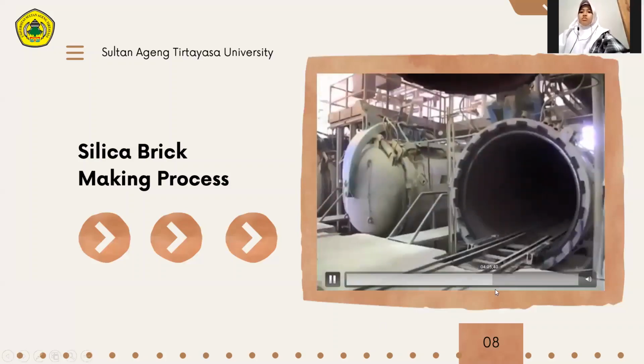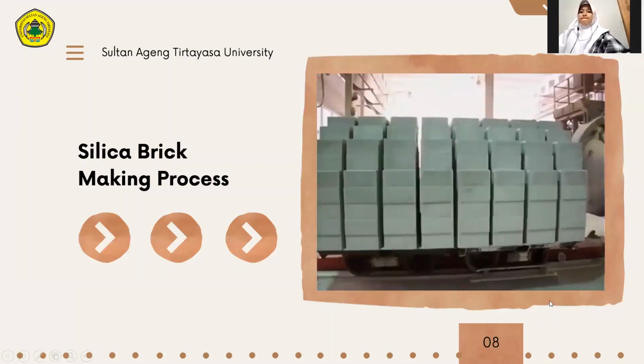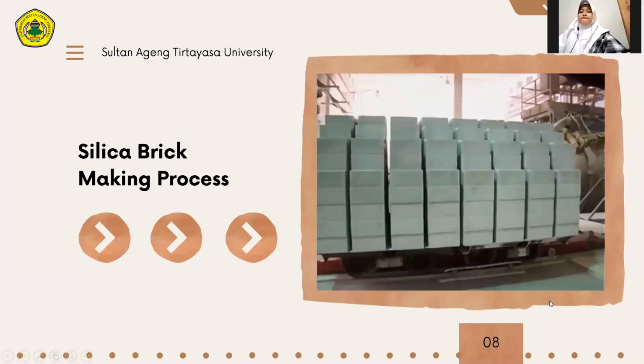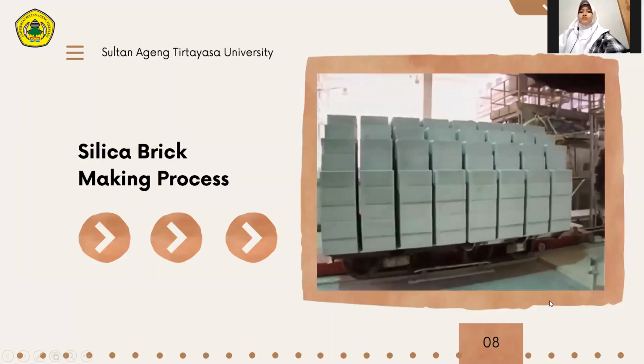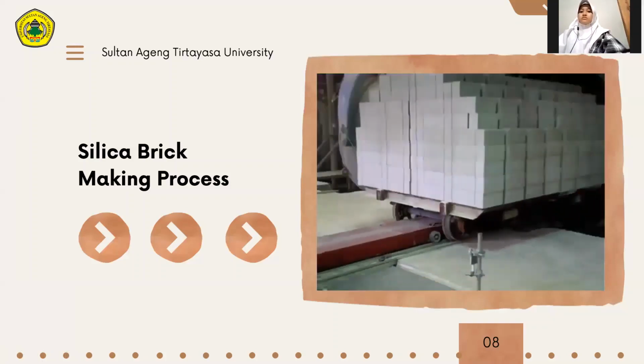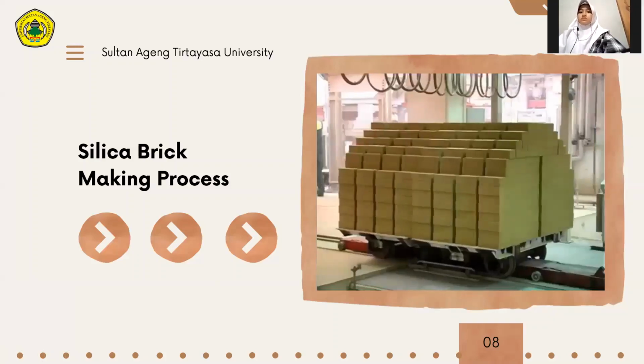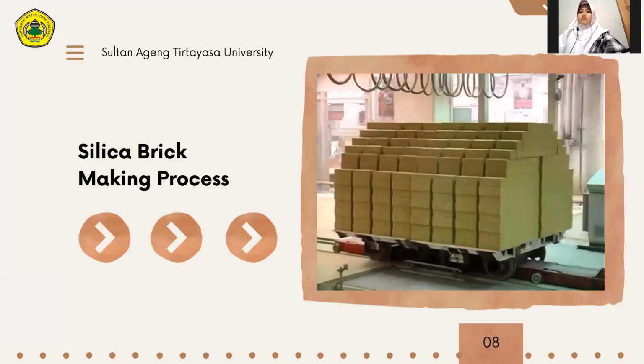Autoclaved in order to have its final strength and robustness. The traverser forwards hardening carriages with sand lime bricks to the section of autoclaving and loads autoclaves. The process of hardening lasts for 8 hours at the temperature of about 200 degrees Celsius with pressure 16 bars.